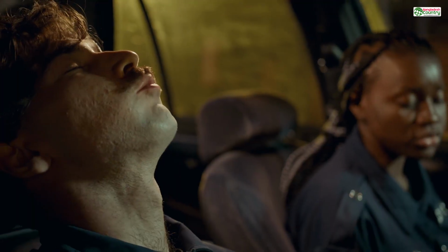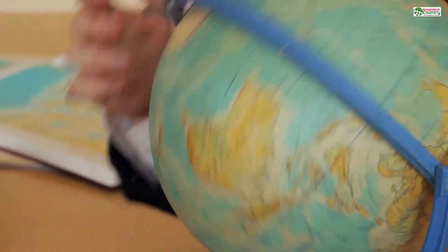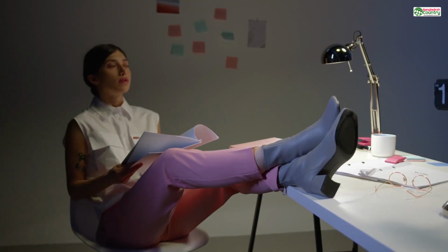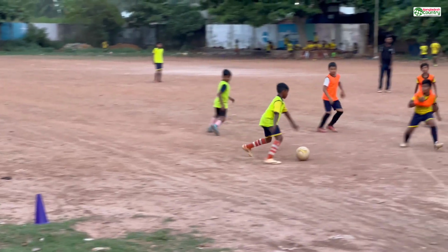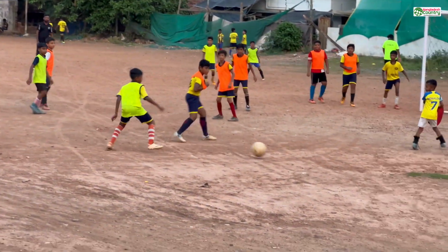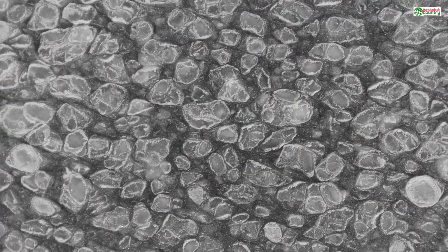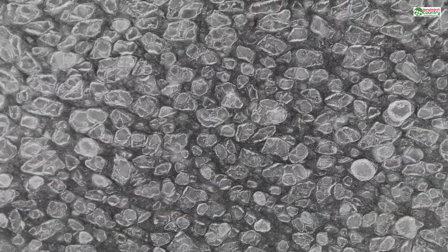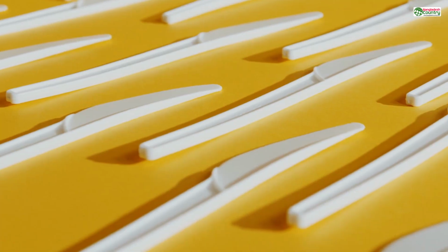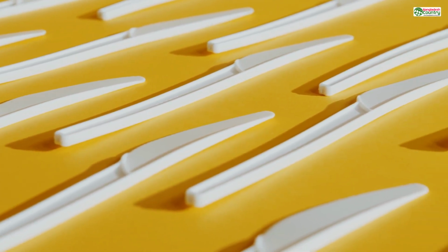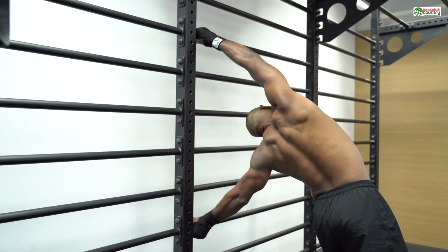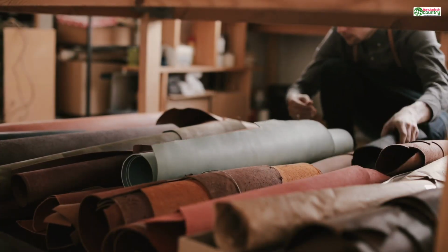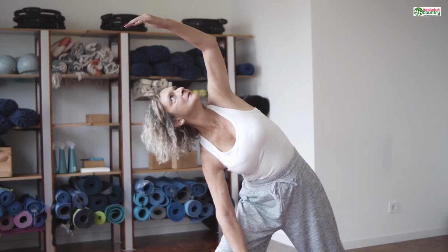Think of nylon as the engineer. This stuff is in a league of its own for toughness and durability. It has a low friction surface, which makes it absolutely incredible for printing functional gears, living hinges, tool handles, or any part that needs to slide, bend repeatedly, or withstand significant wear and tear. It's incredibly strong yet flexible. The material in a zip tie is a type of nylon. You can bend it, twist it, put it under immense tension, and it refuses to break. When you need a part that is practically indestructible under normal use, you choose nylon.